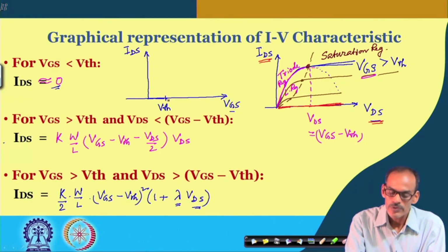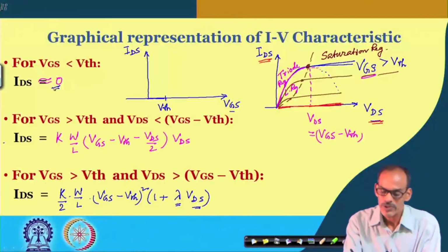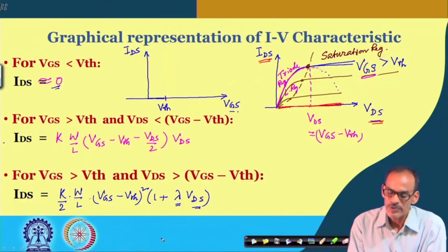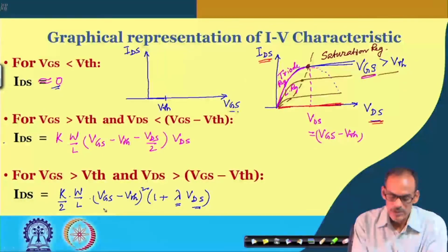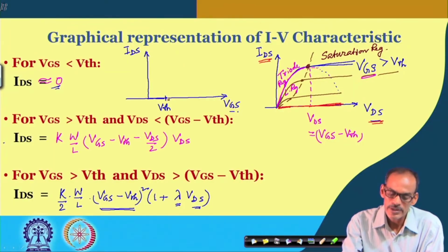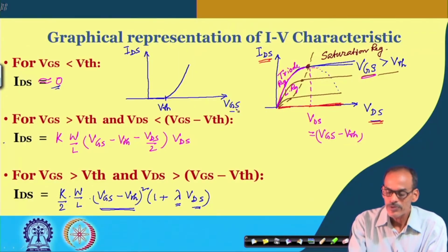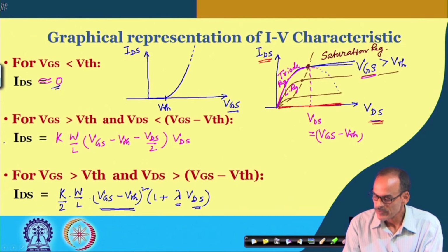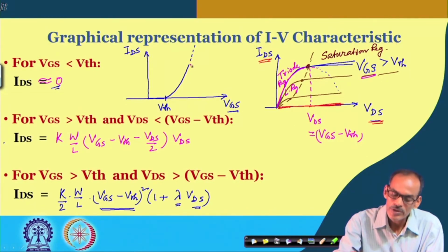And if you are increasing this Vgs, keeping the Vds constant, then you may say that the device starts in the saturation region, and hence the dependency is like a quadratic. And if you go beyond some point where we satisfy this condition instead of this one, the device, instead of really going like this, will bifurcate from that, and it may continue to be a linear one.